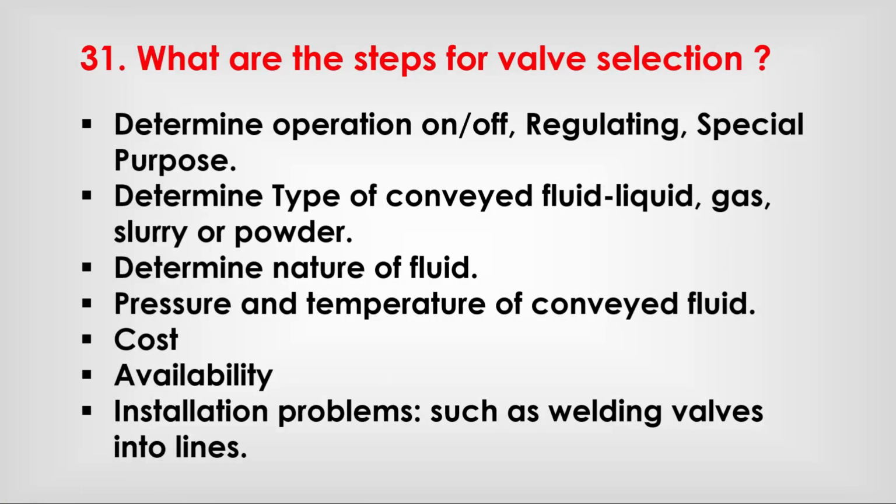What are the steps for valve selection? Determine operation: on-off, regulating, special purpose. Determine type of conveyed fluid: liquid, gas, slurry or powder. Determine nature of fluid, pressure and temperature of conveyed fluid, cost, availability, installation problems such as welding valves into lines.